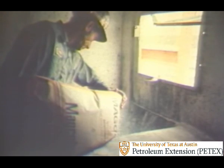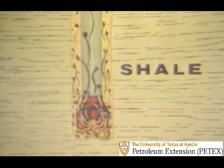How many times have you seen bentonite clay or gel being added to the mud? Well, you may not have known it, but gel is made up of active solids, solids that react with water to give viscosity, gel strength, and fluid loss control. Of course, there are other active solids besides bentonite or gel in the mud. For instance, some of the clays and shales drilled are active. They enter the mud and become part of the mud system unless they are large enough to be removed at the surface.